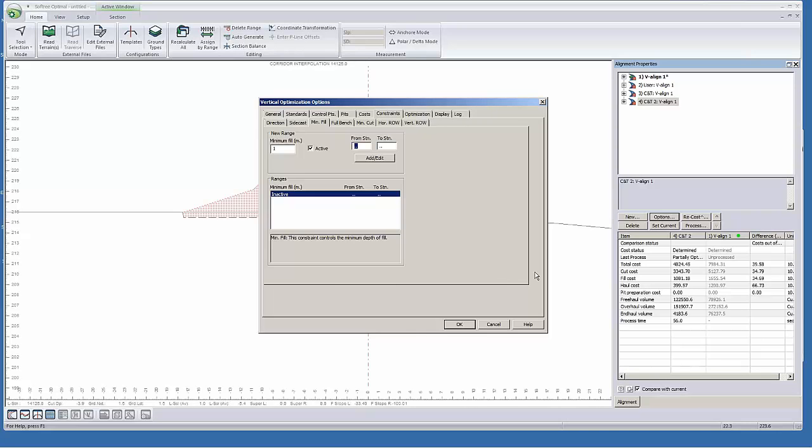Rather than say, I want the elevation of the alignment to be an exact number at that station, you tell it, I want to be at that elevation, but I've got some tolerance. I've got a few meters, 3 or 4 meters of tolerance to get into the driveway. So you're giving it more flexibility, and the least constrained problems are cheaper. The optimizer looks and finds cheaper solutions, so fewer constraints is good.